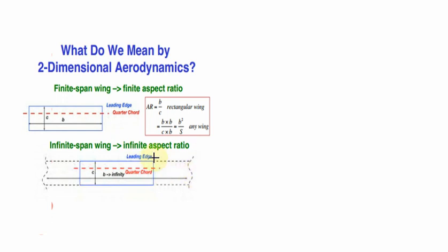an infinite wing section. Infinite wing section means there is no finite dimension, it is an infinite length. So we cannot find the span for the particular airfoil. That is why the aspect ratio is not applicable for an airfoil. That is the main difference between the wing section and the airfoil, we cannot find the aspect ratio for an airfoil.